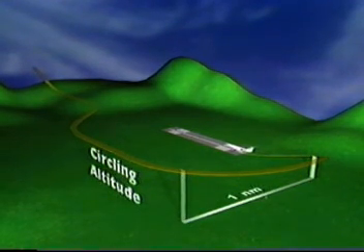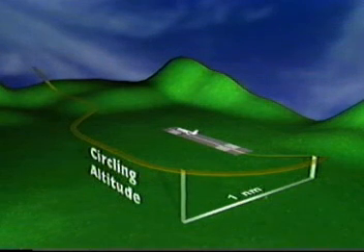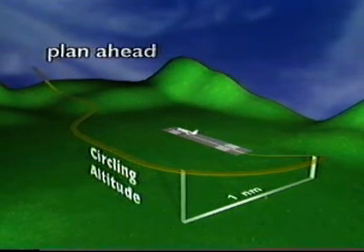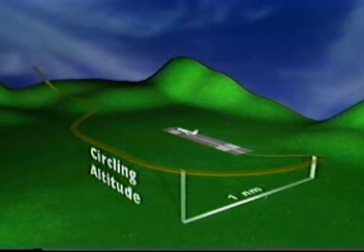Therefore, the most important thing to be observed in a circling approach is to be at the right height and right speed when intercepting final approach. Follow these rules to get it. Plan ahead. Estimate how many seconds after passing the beam threshold you will extend the downwind leg. Estimate how much you must descend on the base leg.